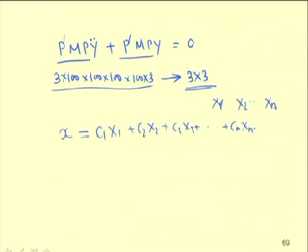If we are considering n number of modes, then the resulting free vibration of the system can be written as the summation over i equal to 1 to n of C_i x_i, where C_i is the modal participation of that particular mode. One can find this modal participation by using the eigen property of the system.